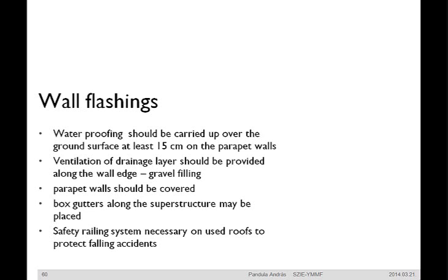The parapet walls along the edges of the roof should be covered by some kind of waterproofing system. Application of aluminum profiles pressed or bent from sheet can be recommended. However, special attention should be paid to the upper covering, since they are usually made of elements, so the connection should be watertight.